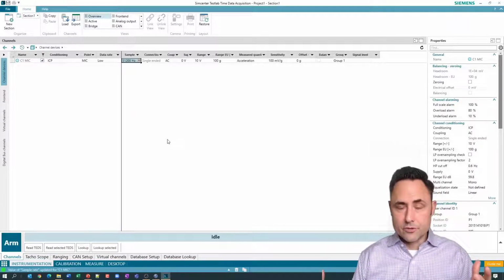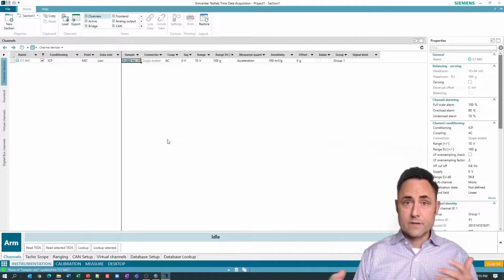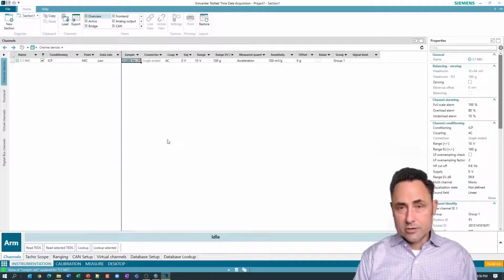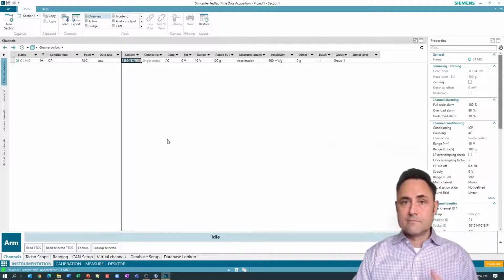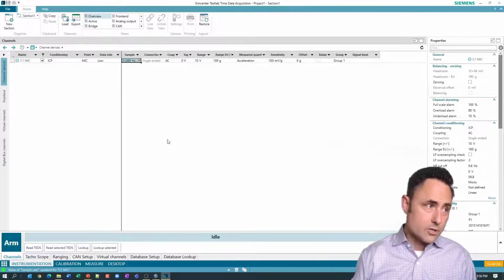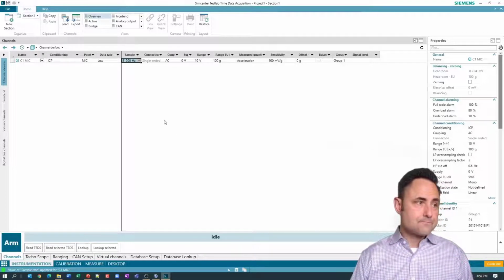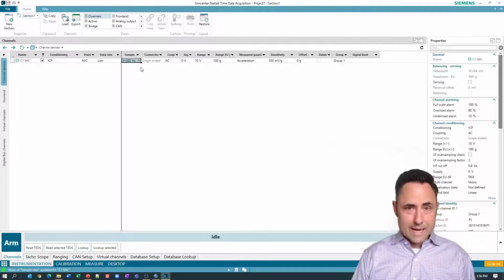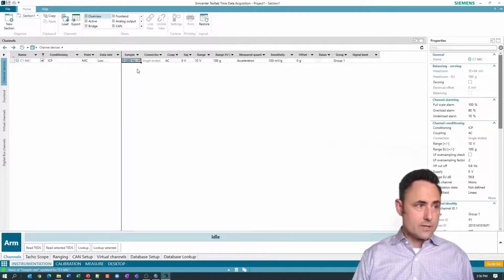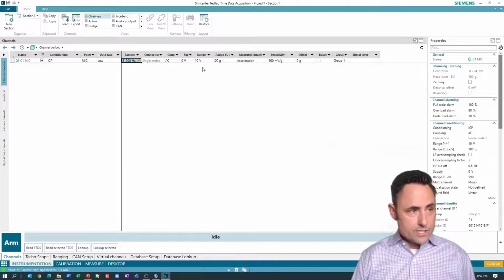So typically if you're measuring a mixture of accelerometers and microphones, you don't necessarily want to sample those the same because you're not usually interested in vibration data out in the frequency domain nearly as high as you are a microphone. Okay, so that's why we just call them low and high. In this case, I'm just going to maximize that out just like I did last time for the same reasons. I want to sample wide open. And then you see I've got a range. I've got my measurement